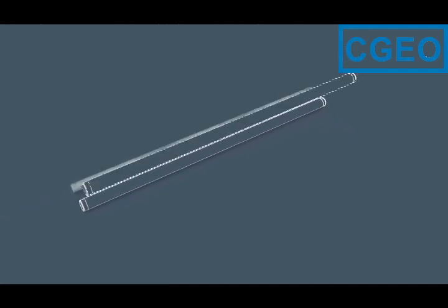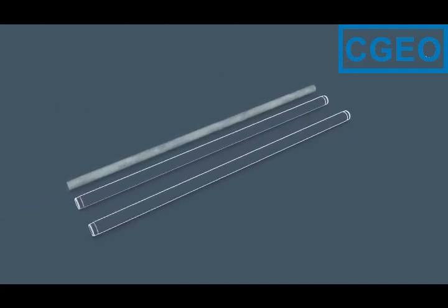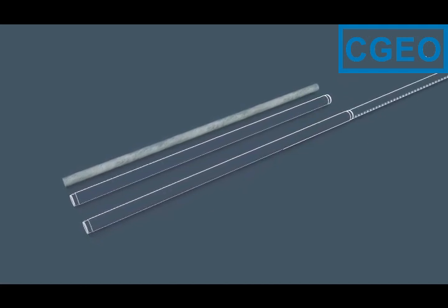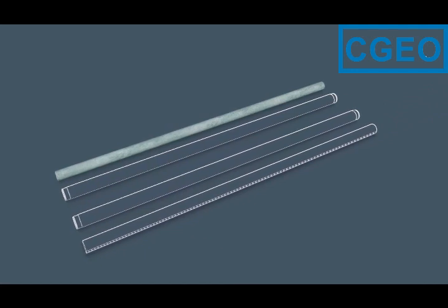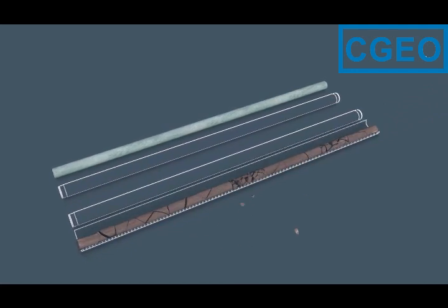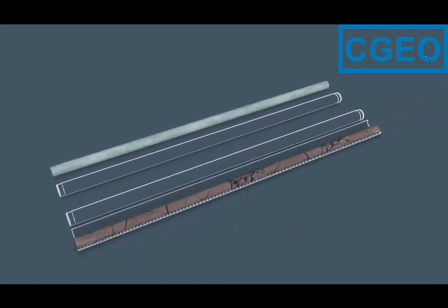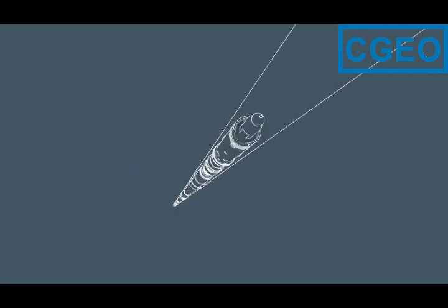To prevent that, a triple tube core barrel can be used, which means there is an extra inner tube inside the normal inner tube. This can be pumped out and then opened in 2 halves to collect the soft core sample. While emptying the core sample, a second inner tube assembly can be reinstalled.